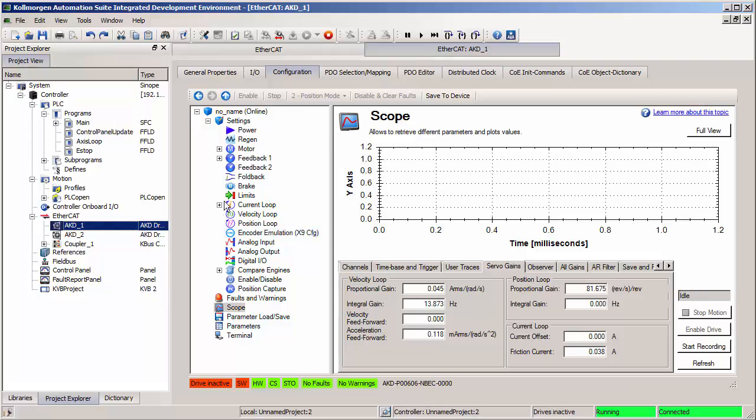That's also why you will not see certain screens such as service motion or our auto tuning screen. You cannot use these while a program is running, so we auto hide those. If you would like to use those screens, you must use the online configuration mode through this button here, which you can only do when the program's not running. We'll cover this in a separate video.